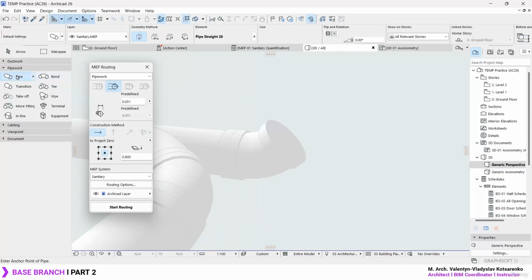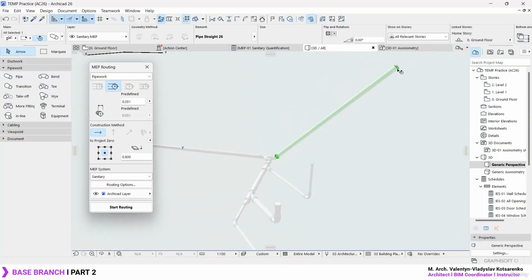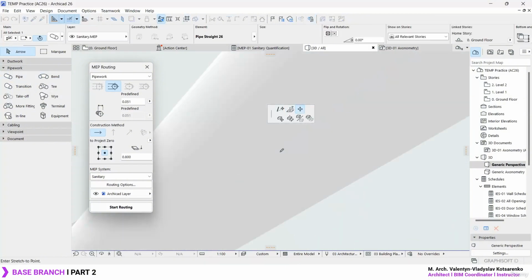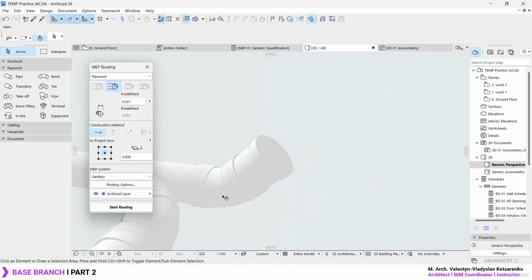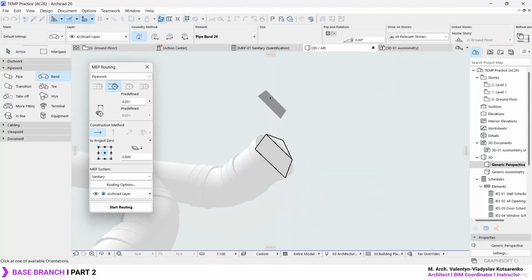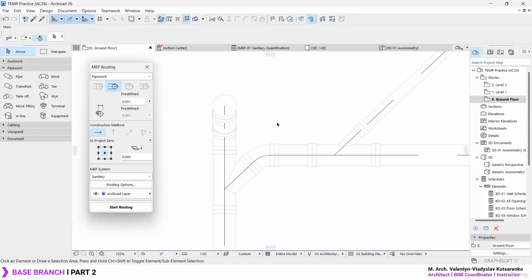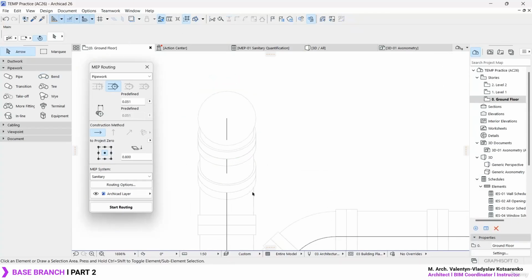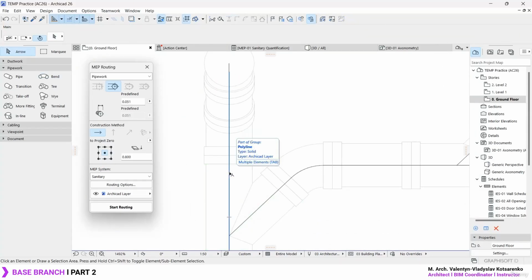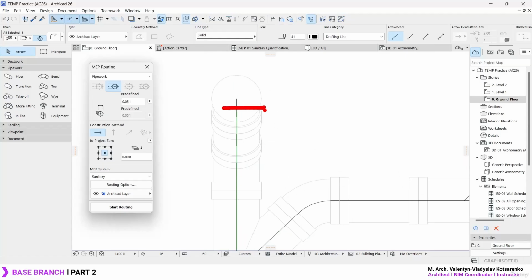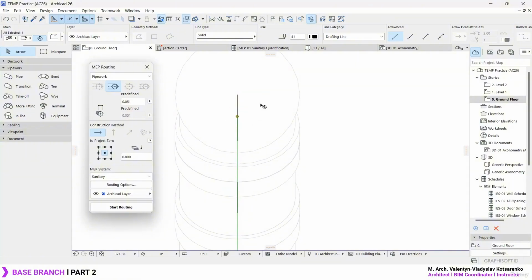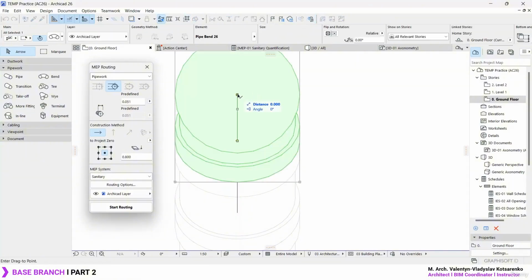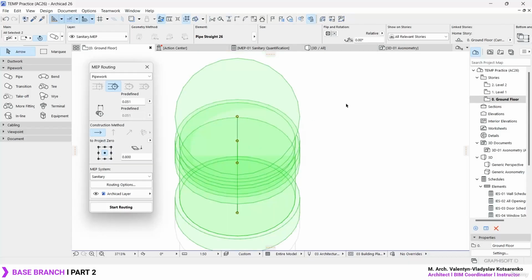Let's go ahead, maybe set up a basic pipe, which is going to be just a small trim over here. Let's move the node. And then let's position the final elbow vertically. Now in 2D, we can position this a little bit better because if I remember, we also got a reference line over here, which is going to mark where this elbow needs to be positioned, which is this point over here. So how about we maybe select this one, move this a little bit until it intersects with the line.